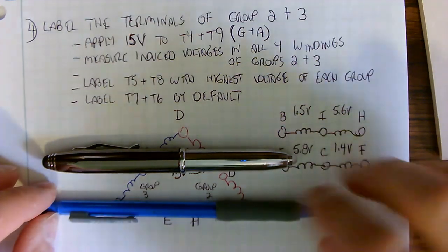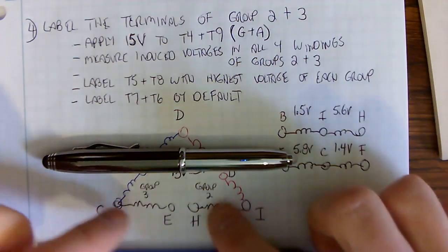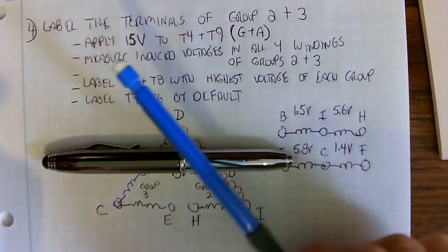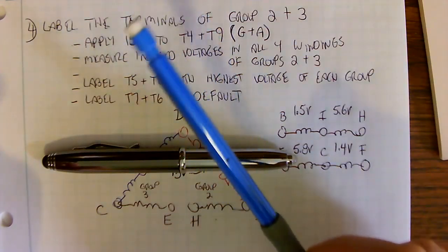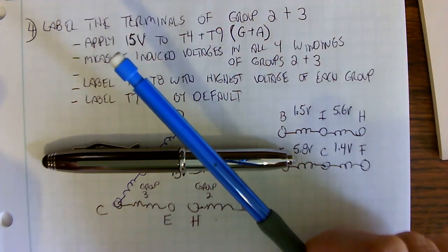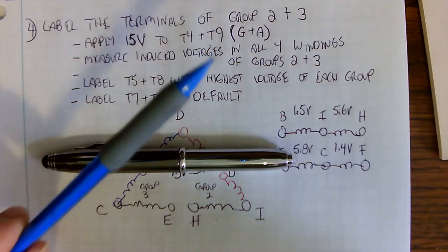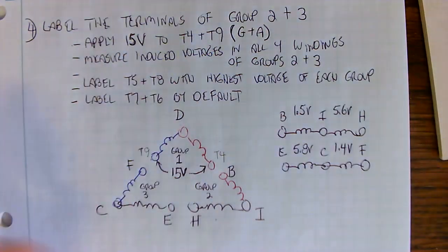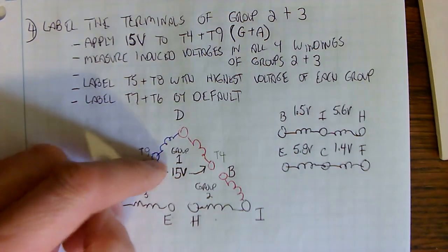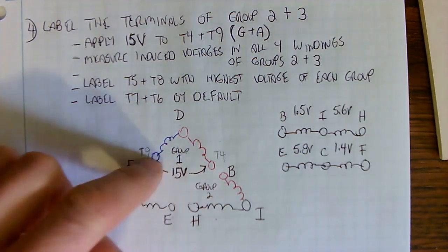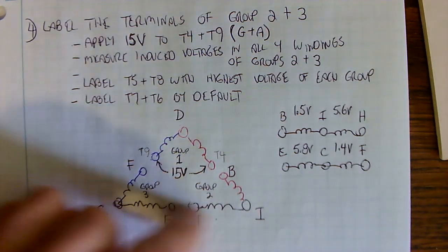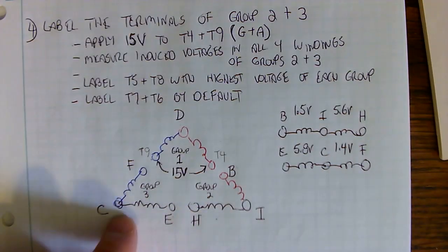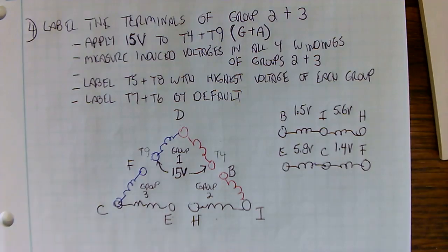They're parallel with each other, so that's why these windings are going to be induced a higher voltage, because these other ones, they're not quite perpendicular, but they're not parallel, so they're going to have less voltage induced into them. So that will give you some kind of way of thinking about this when you do this process, that this going straight across here and this going straight across here will be parallel, higher voltage in these phase B windings here.